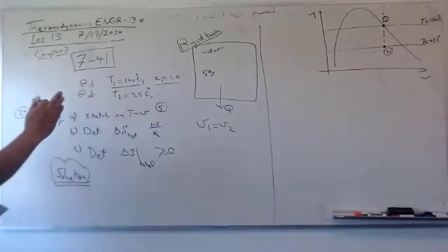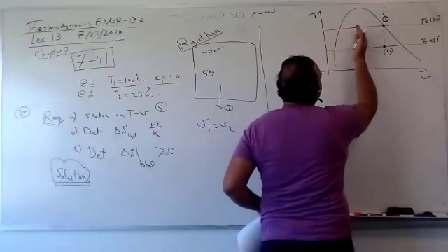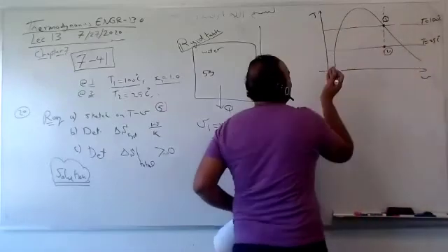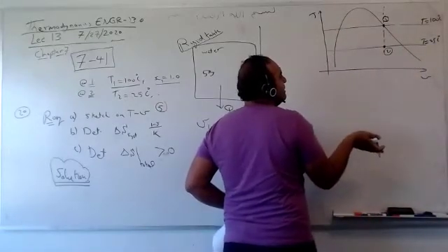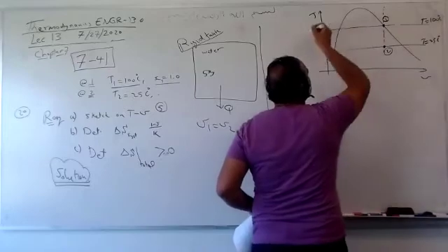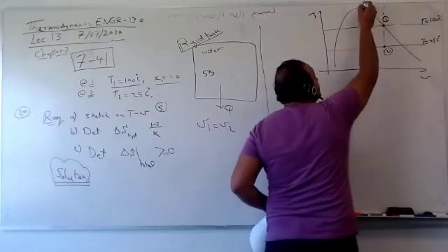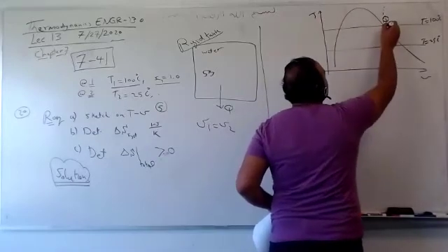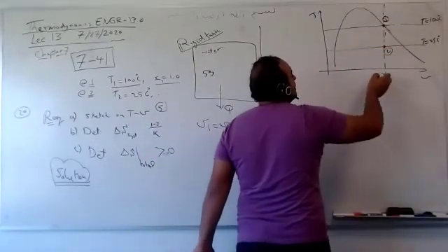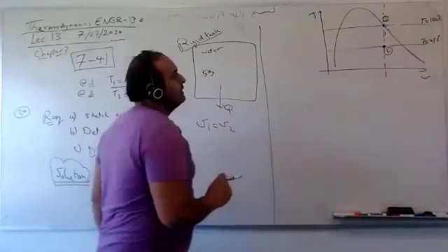You know, this curve, this is x equals 0. There is no x here. 0, 0.1, 0.2, 0.3 up till 1. There is no x here. So you know 100 Celsius. Guys, if I told my son, if he's 4th grade, 5th grade, he knew this is line constant y. This is constant y. What constant temperature? This is the first point because x equal 1 and T equal 100. Rigid tank, it means move vertically, anywhere vertically. I cool it down. Of course, temperature decreases until 25. It's here. Does it make sense, guys?